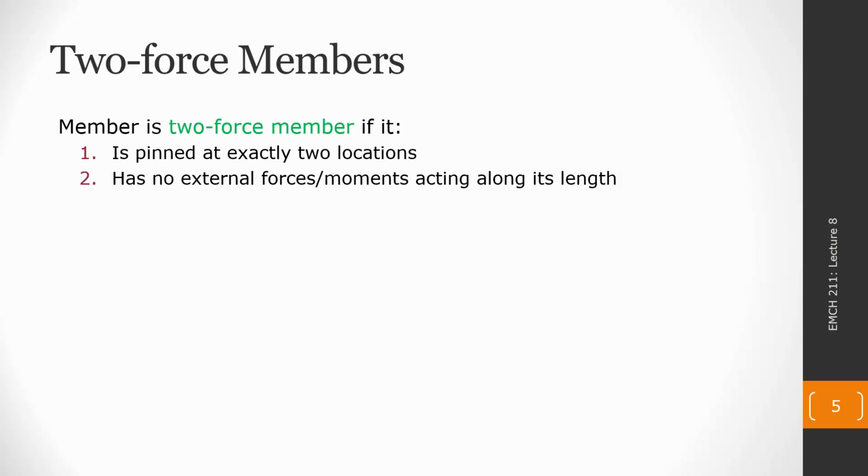Additionally, that member can have no forces and no couples acting along its length. Again, this was another requirement in our truss problems, that the loading was only occurring at pin connections, not along the length of a member, and we were ignoring the weights of the members, which would also typically have their center of gravity along the length of the member itself.